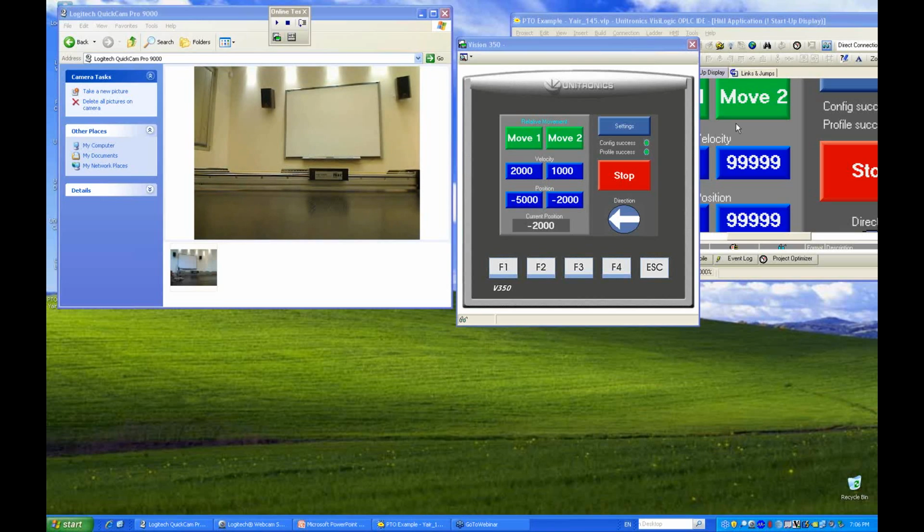If it is PNP mode, it can be converted relatively easily with the addition of one transistor or even one resistor, which I don't like too much, but it can be done. But usually, because it's faster, they use the NPN mode, and any such driver with such an interface can be used. There is no limitation I know about.